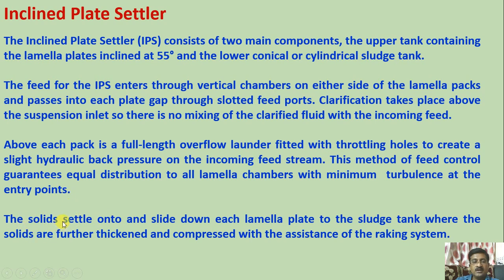The solids settle onto and slide down each lamella plate to the sludge tank, where the solids are further thickened and compressed with the assistance of the raking system. So the raking system is there, which moves all this sludge, and it is taken for further operation.